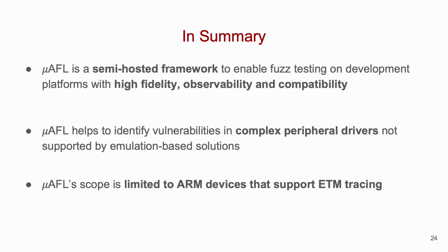While mAFL accounts for resource constraints and bare metal nature of MCU firmware, its solution is specific to ARM devices that support ETM tracing, not taking into account diversity of hardware in microcontrollers. This motivates a more general approach to semi-hosting that is compatible or at least portable to a diverse set of microcontrollers from different manufacturers.